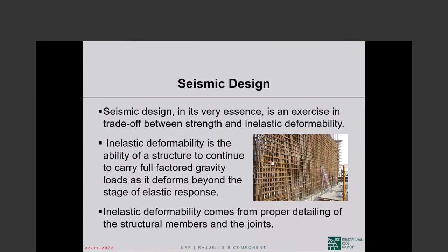Some basic stuff that I have gone over with you probably more than once. Seismic design, in its very essence, is an exercise in trade-off between strength and inelastic deformability.